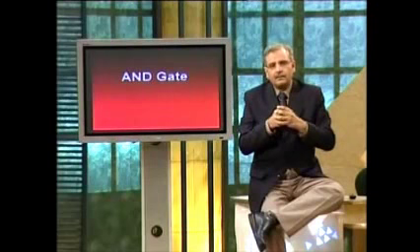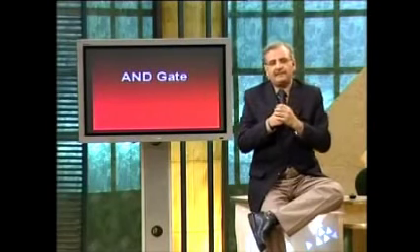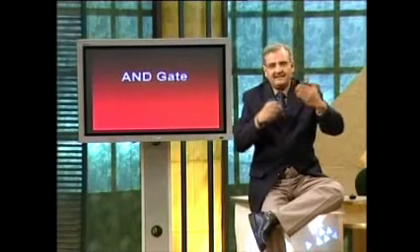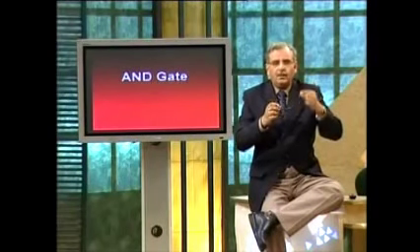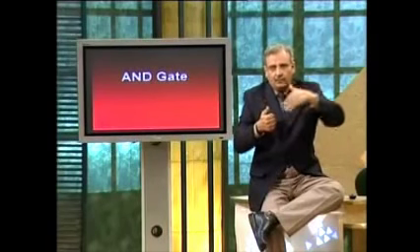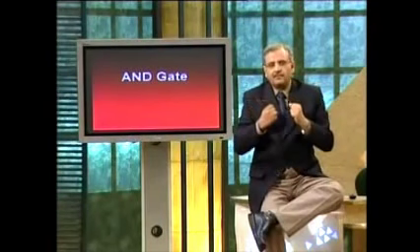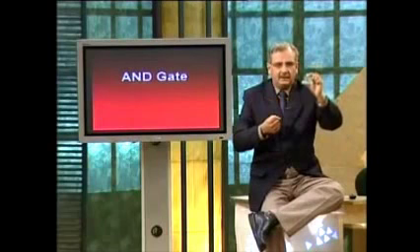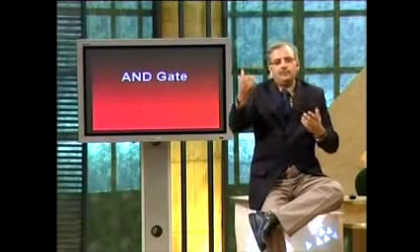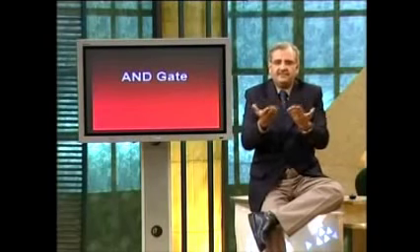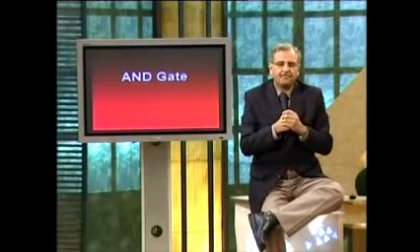Which function is this basically implementing? Well, if you remember, when we talked about binary multiplication, exactly this was happening. When we multiplied 2 single binary bits, then when both the bits were ones, only then the answer was a 1. For all other combinations, the answer was a 0. So if someone asks you to implement multiplication for binary numbers, of course, you can use an AND gate. It implements the multiply function.